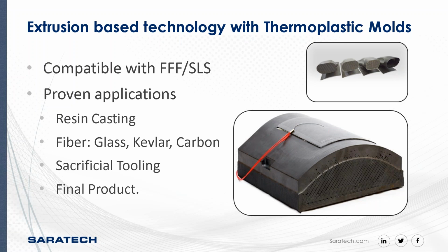The material you see in the above image can be dissolved once the composite is wrapped and cured, and that leaves you with a final product that you can use. And you can see the different stages in the image as the part is printed to where the sacrificial tooling from the inside is removed from the fiberglass exterior.